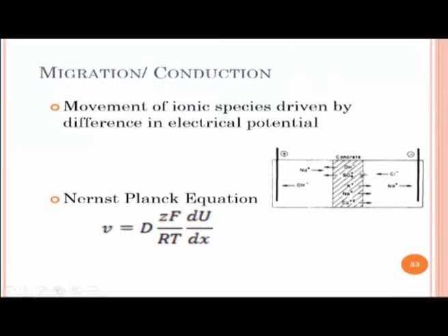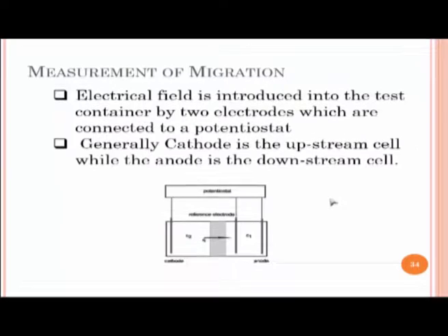Okay, so this is a snapshot of a concrete which has two cells here. One is a positively charged cell, one is a negatively charged cell. That means you have applied a potential difference between two electrodes. Your concrete is sitting inside in a saturated condition and you have different ions moving in different directions. I will describe the test method for which this applies in just a minute.